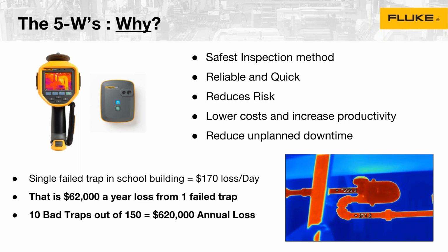And obviously avoid downtime. There are situations where avoiding downtime is critical. One that comes to mind is a recent facility that had a small vibration program they were putting in place with a bunch of chilled water motors and pumps. They were really focused on the vibration program, doing this on a regular basis. And I told them, have you ever considered using thermal in conjunction with your vibration? Because not all issues are related to vibration.